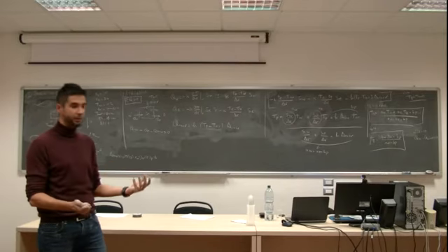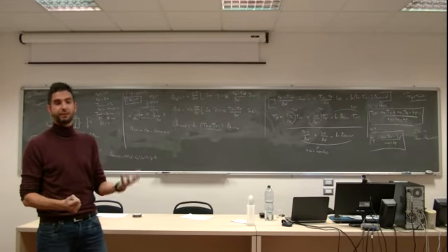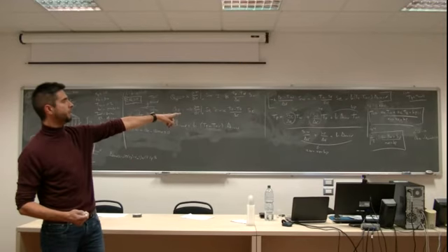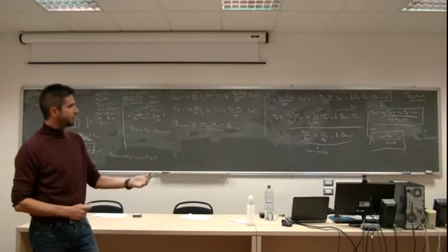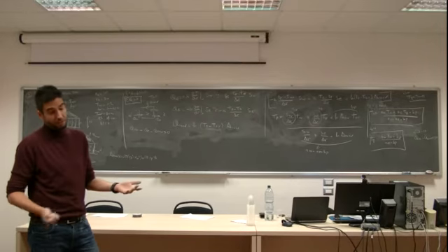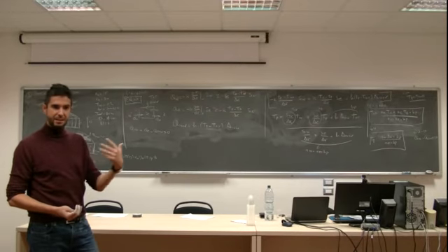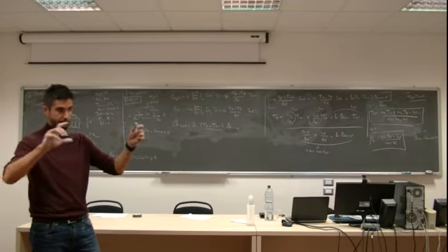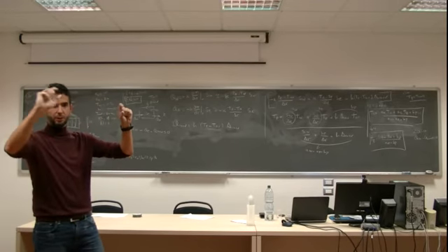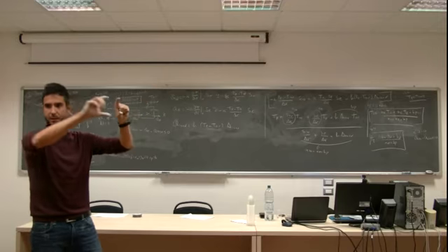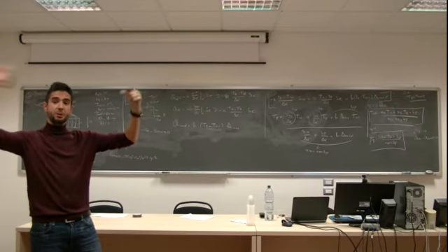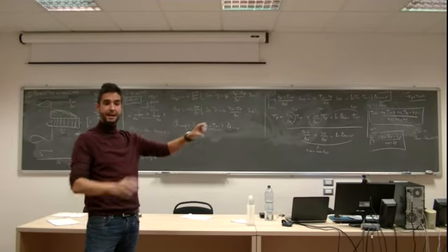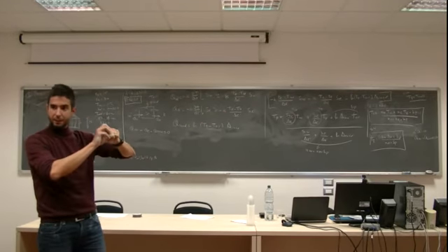And the strength of the numerical tool is that it is iterative. I'm calculating T1, but to calculate T1 I need T2, which I don't know. Okay, I will assume a map of temperature. I will assume values of T0, T1, T2, T3 until Tn. With this assumption, I will calculate the values based on my equations and I will get a map.